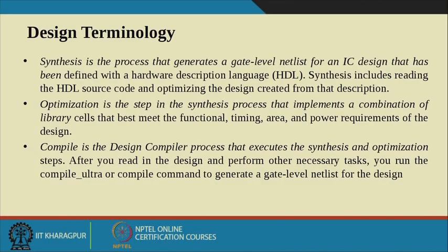Synthesis is the process that generates a gate level netlist for an IC design that has been defined with a hardware description language. Synthesis includes reading the HDL source code and optimizing the design created from that description. So that means whatever logical expression I am giving through this HDL code will now be described using the basic gates. That is the basic of synthesis.